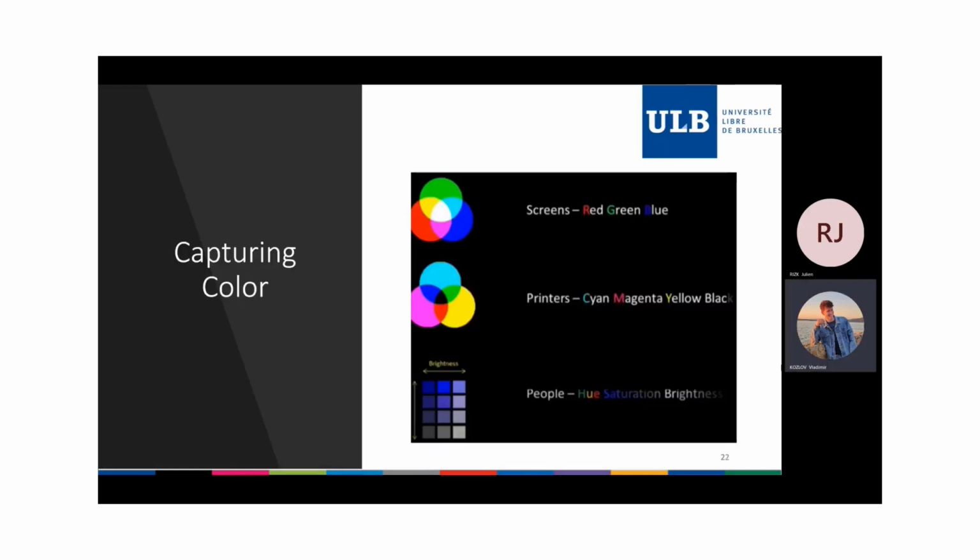Three models of colors are used for the treatment of digital images: the RGB color model for monitors, the CMY for printing, and the HSI, also used for monitors and to separate the information relating to the gray levels and color. However, each photo site is colorblind and only keeps track of the total intensity of the light that reaches the sensor. The solution is to capture the three primary colors separately and combine them to create the full spectrum.